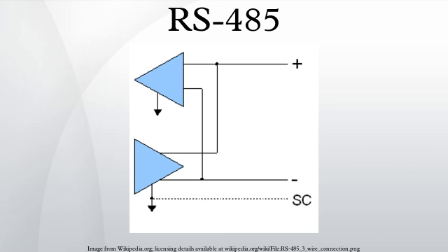If a star configuration is unavoidable, such as when controlling multiple pan-tilt-zoom cameras from a central video surveillance hub, special RS-485 star hub repeaters are available which bidirectionally listen for data on each span and then retransmit the data onto all other spans. Somewhere along the set of wires, pull-up or pull-down resistors are established to fail-safe bias each data wire when the lines are not being driven by any device.